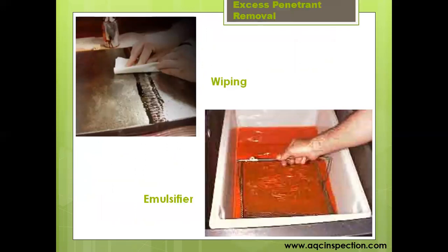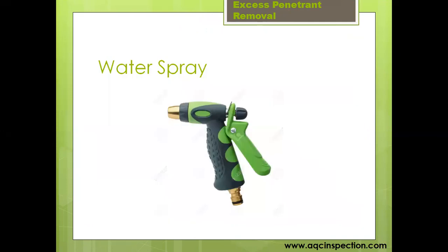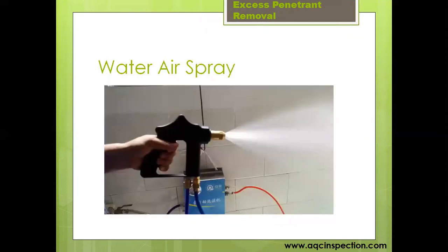Pictures of excess penetrant removal are given here. Wiping, emulsification, water washing. Water washing can be done by water guns, either water spray or water air spray.